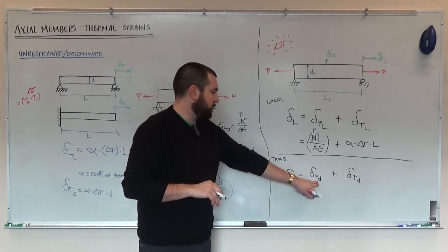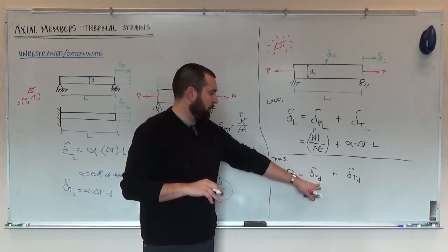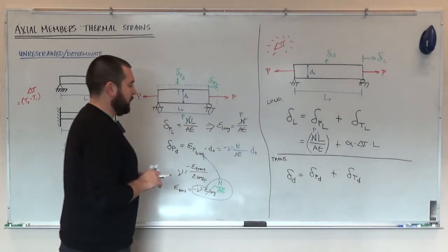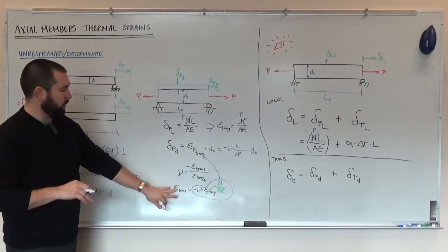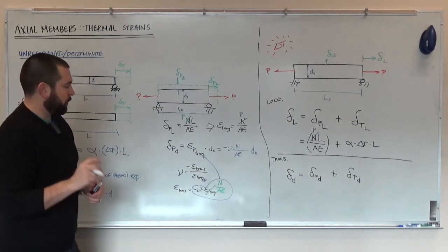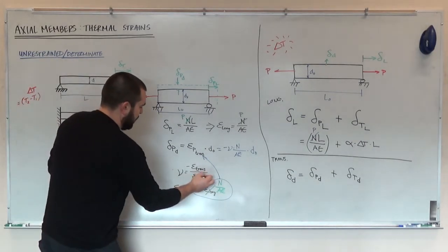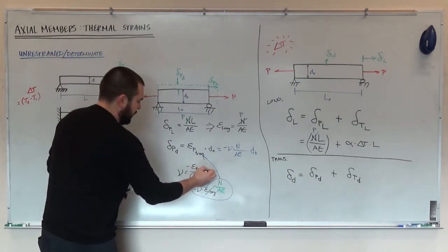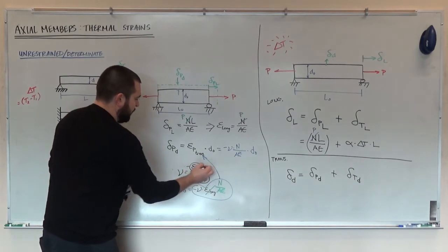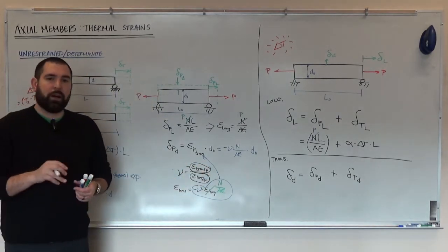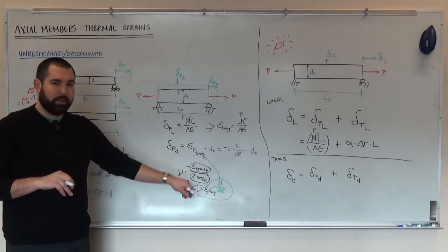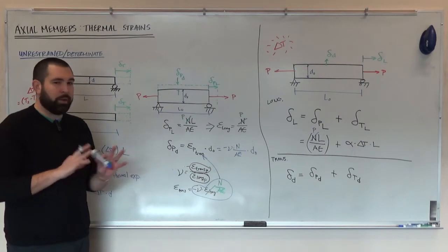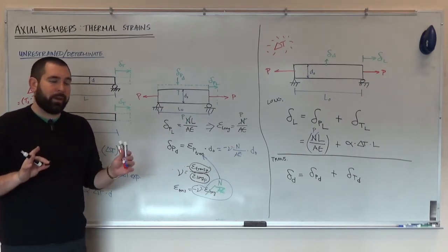So here, the change in depth, the change in width due to the externally applied force, that's due to Poisson's ratio. That's all of this work that we just did right here. But the critical part, just like I mentioned before, is that Poisson's ratio is only relating, and I can put a P here as well, it's only relating the strains caused by the externally applied load P. This calculation here ignores completely any thermal effects going on.